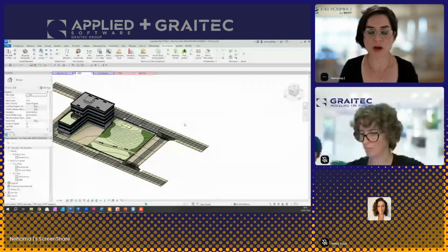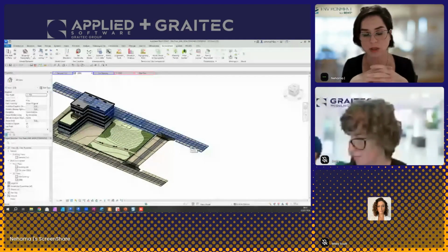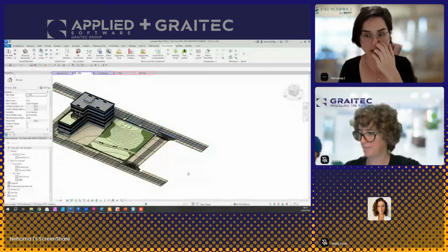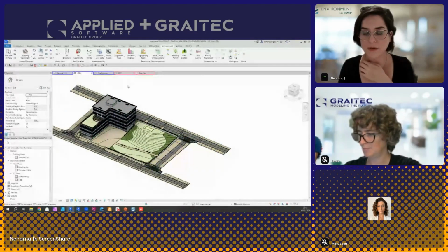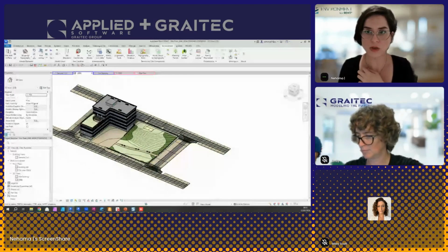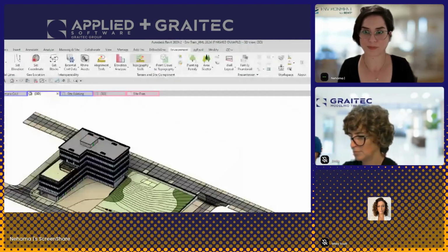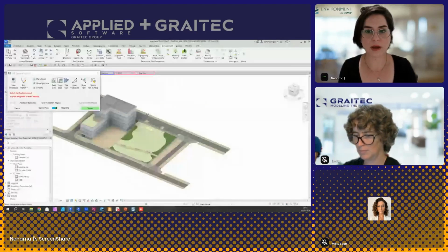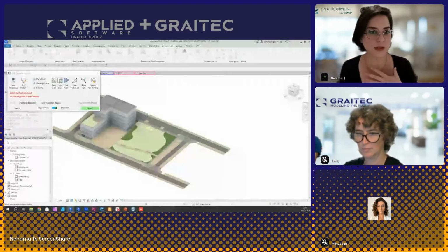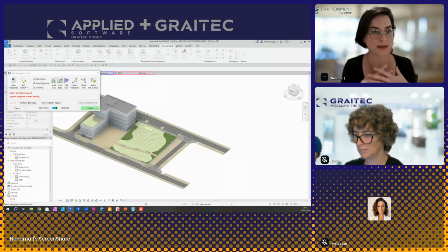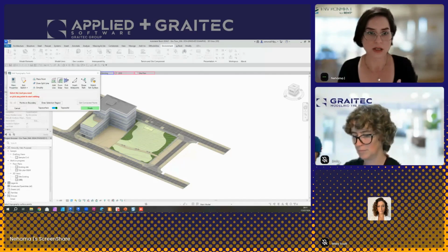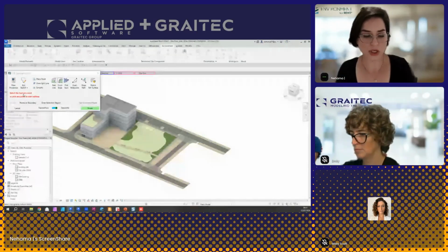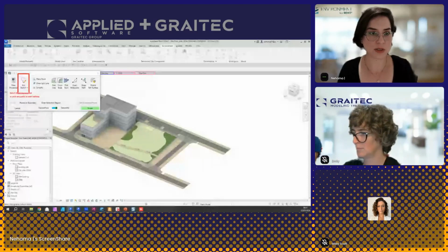And what we're doing with environment for Revit, we're marrying the idea of a topo solid and a reference surface. And basically, to create that, we just need to use the topography tools over here. So as I open the topography tools, you can look at them as a tool to create the reference surface and the topo solid at the same time. And the reference surface is like an abstract thing, but it's really in there. So let's take a look. I'm in the 2024 version, and I can actually use the edit sketch.